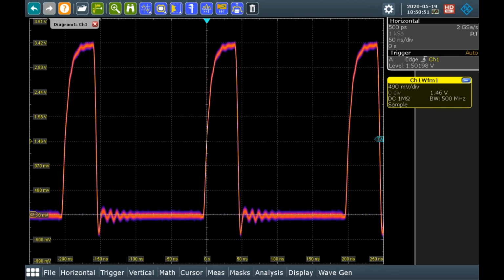So a lot of times, something like an RTO or an RTP can be used to get those high-speed digital signals as well and get those nice recreations, but you also see the live changes. So if you were to touch a trace, or move a cable or rotate your device, you're able to see those changes real time. It becomes a little bit different way to think of how fast is my oscilloscope, how reactive is my oscilloscope.